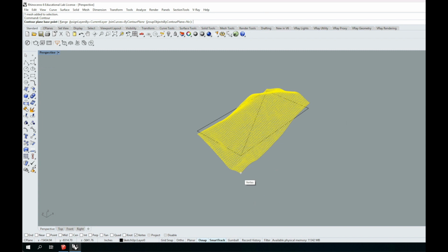And after I've done that, I'll move out to the right here. Now I want to make sure that I'm in line, so let me turn on my ortho snap. And I'll make sure that I'm just moving my mouse out to the right side here, such that I'm in line with the x-axis. So we'll go ahead and do that, and I'll make a single click.